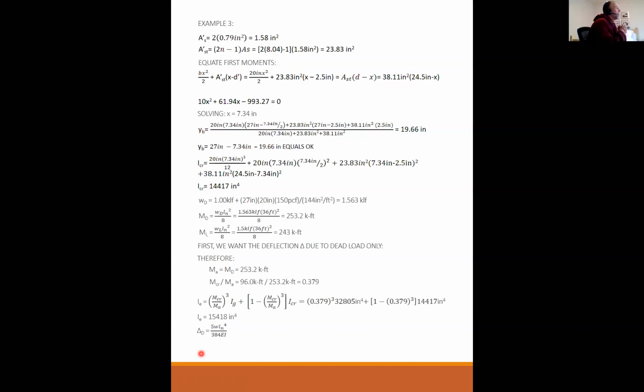That is the law of nature. No, it really is. It's just kind of how we do it. But it comes from anytime that you have an area, like one bay. Say your columns are 30 feet apart by 40 feet apart. So your bay is 30 feet times 40 feet. The loading in any particular area is always given as pounds per square foot.